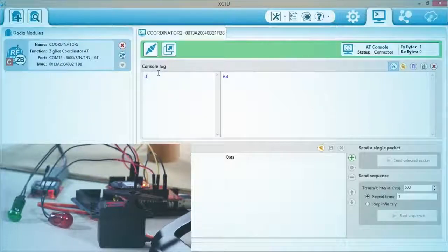Now if I send it a capital G, which you can see there in this area, right? So I typed in whatever that was, a D. If I type in the capital G, we should first see that it saw something in the buffer. So the red light should light, and the motor should move the same way it did. But it should then look and see that it was in fact the capital letter G, or ASCII representation thereof, and it should then turn the green light on and go faster. Right. So here I go.